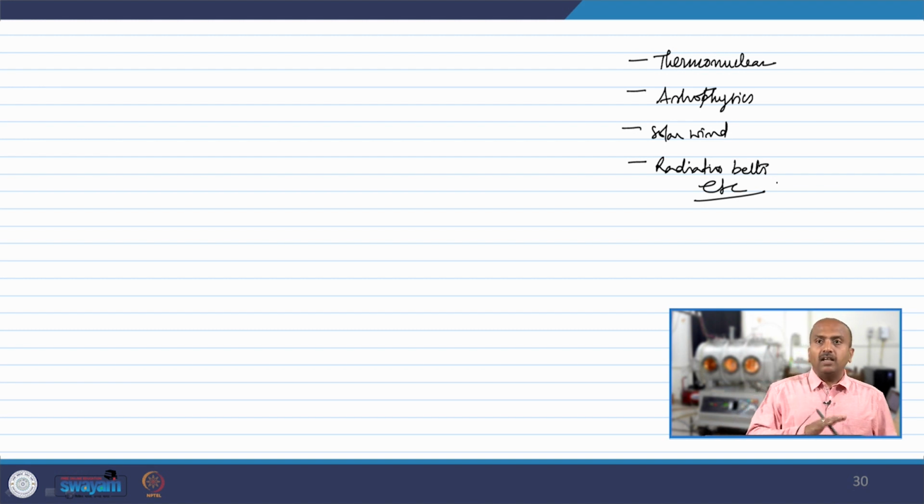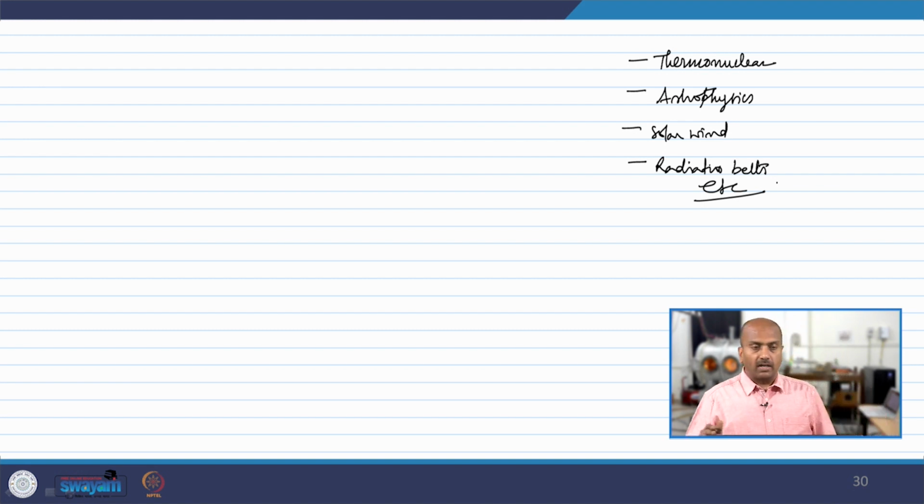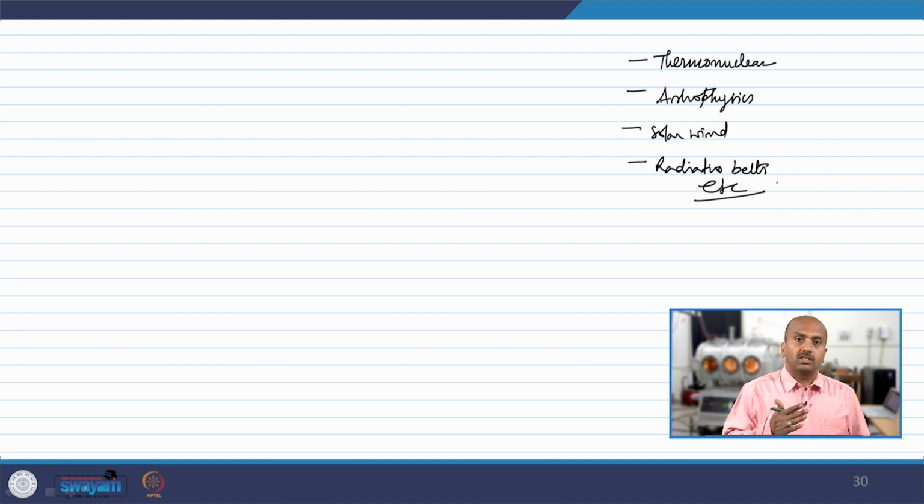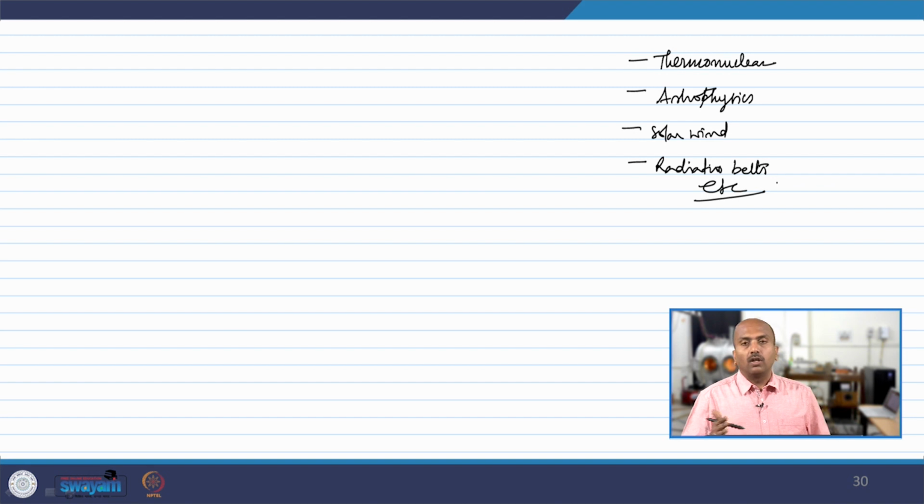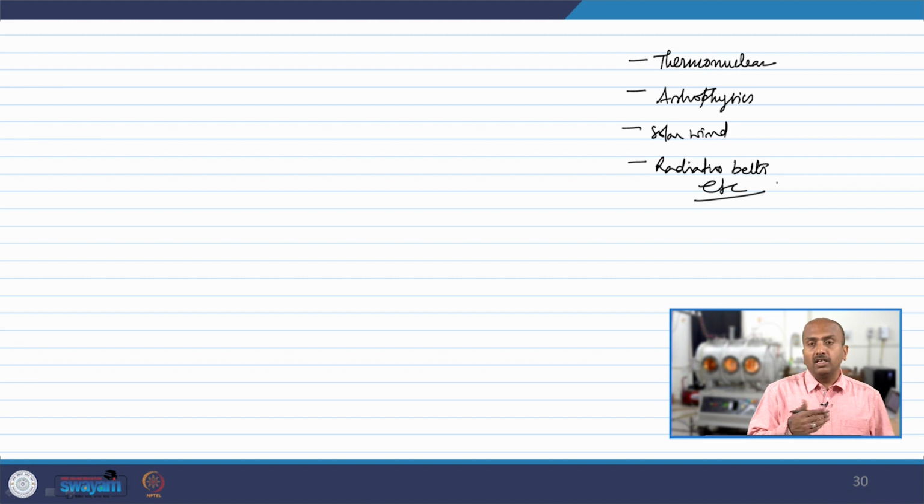Now, if you are able to write the equilibrium solution, fine, but that does not guarantee that the system is stable or not. How do you test it? You put a small perturbation to the system, and if the perturbation is growing with respect to time, then you call that unstable. So, a system coming back to equilibrium is stable, and a system not coming back to equilibrium in the presence of perturbation is unstable, right.